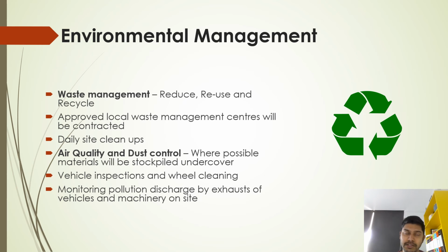So looking at the air quality and dust control, we'll make sure we stockpile materials on site undercover so that they won't be exposed to open environments. Also, prior to exiting the site, we will conduct vehicle inspections and we'll make sure the wheels of those vehicles are cleaned. And during windy weather, rubbish bins in the open environment will be thoroughly covered. And also the machinery exhausts and the exhaust of vehicles will be subjected to regular maintenance to ensure minimum pollution discharge.